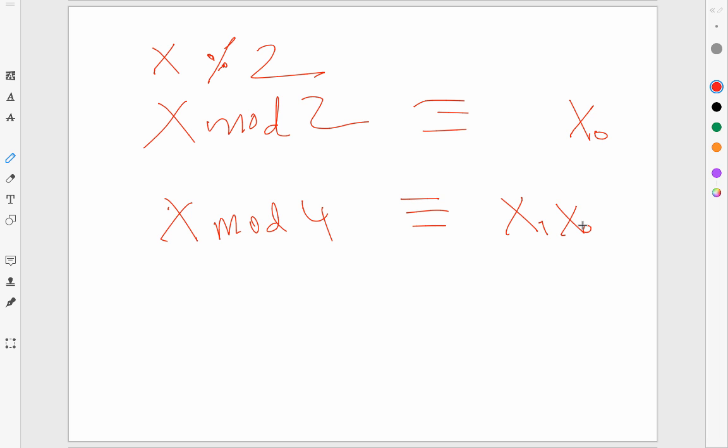Anything else? Yes. How would you draw a splitter? You can kind of mimic what Logisim does. As you might notice, at least from the first homework, I don't draw by hand in the solutions, I use drawing tools. But in an exam setting, have the wire coming in, have it fork out, put the index numbers on the forks.